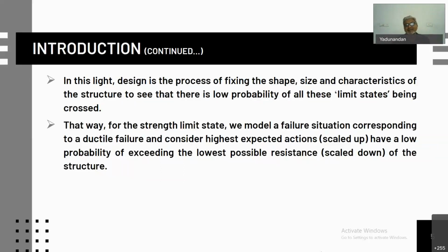That way, for the strength limit state, we model a failure situation corresponding to a ductile failure and consider the highest expected actions, which are scaled up to have a low probability of exceeding the lowest possible resistance of the structure.